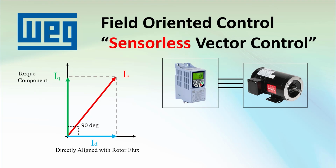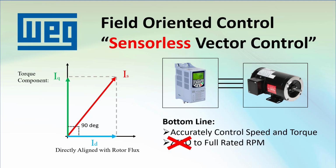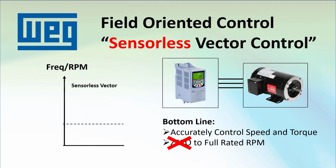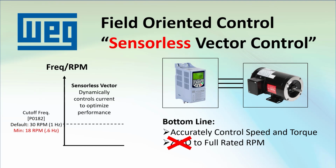Of course, for the rotor to have enough of a magnetic field for the drive to work with, it has to be rotating faster than some minimum speed. Let's show that graphically. Above some minimum speed or frequency, the drive can use sensorless vector to dynamically control the current to optimize the speed and torque of the motor. Parameter 182 contains that cutoff frequency, and it defaults to 30 RPM, which for our 60 Hz setup would be 1 Hz. The programming manual for the CFW500 drive recommends staying above 18 RPM, which for our 60 Hz motor would be around 0.6 Hz. That's pretty good, especially when you compare it to volts Hertz, which struggles below a few Hertz.